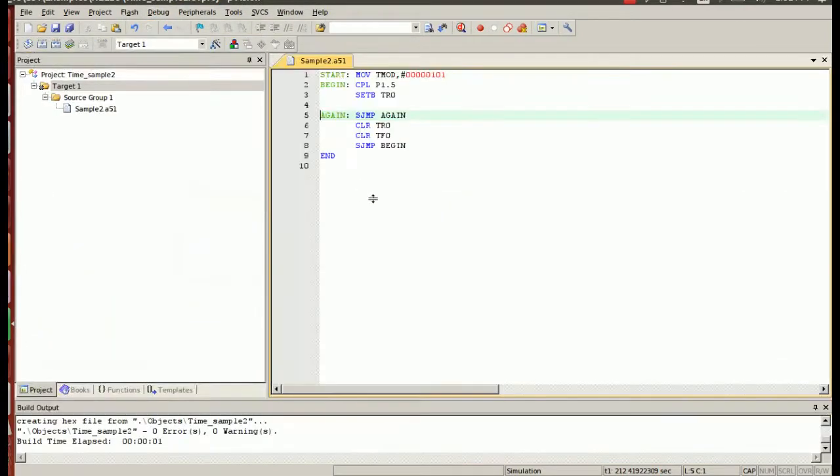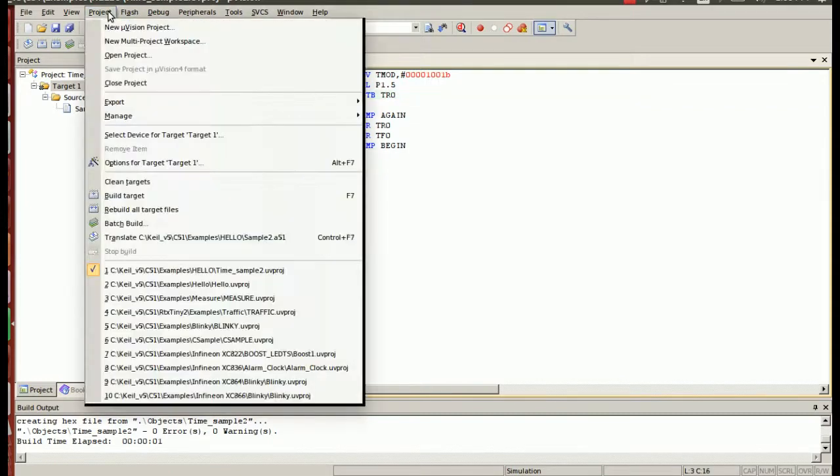Now earlier we talked about the significance of gate. Now we will set the gate bit as 1 and see what happens for the timer. So bit number 3 is the gate bit. Bit number 0 and 1 are mode. Bit number 2 is the C/T bar, and bit number 3 is your gate. So I will put it as 09 hexadecimal, or I'll put it as this binary. Let me now compile this particular program.